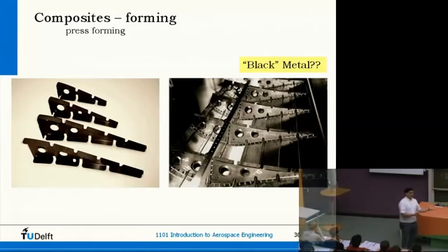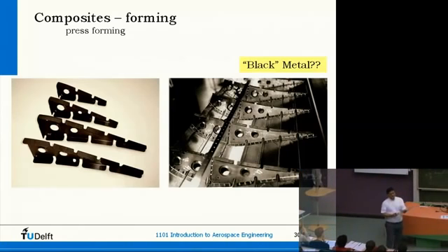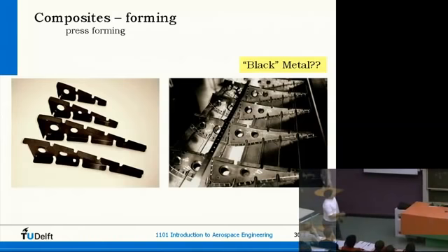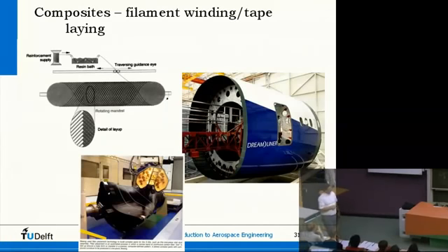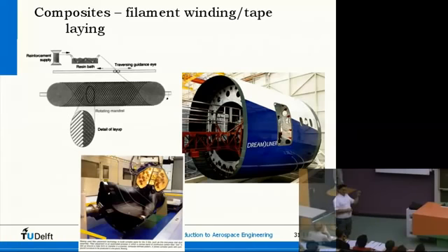And before the forming operation, we heat the material to make the thermoplastic soft, so it can indeed form. It's only possible for thermoplastic materials. These are typical ribs, as you can see here in wing structures. Filament winding is also possible, or by rovings, some kind of very thin ropes, and sometimes even with tapes. This is made by filament winding or tape laying, and this also.